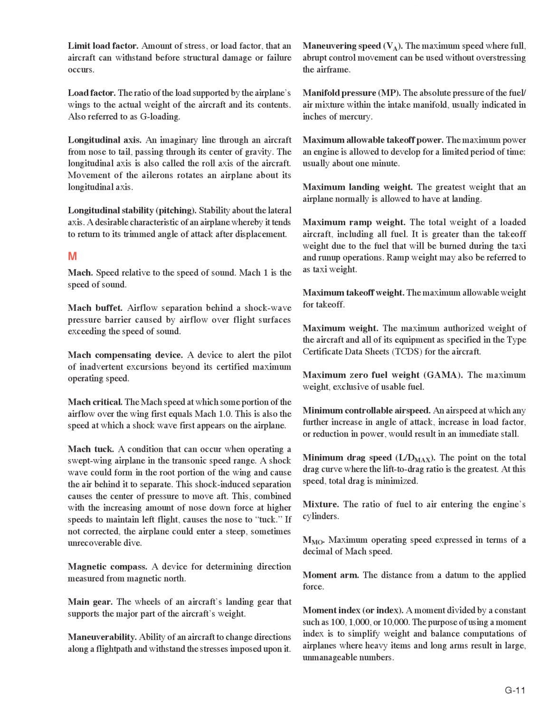Mach tuck. A condition that can occur when operating a swept-wing airplane in the transonic speed range. A shock wave could form in the root portion of the wing and cause the air behind it to separate. This shock-induced separation causes the center of pressure to move aft. This, combined with the increasing amount of nose-down force at higher speeds to maintain level flight, causes the nose to tuck. If not corrected, the airplane could enter a steep, sometimes unrecoverable dive.